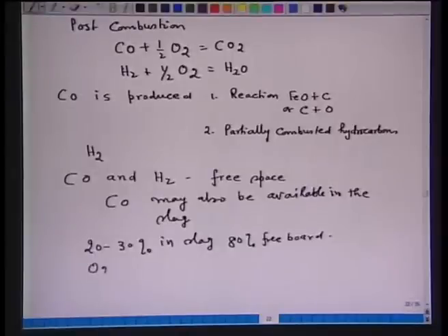That means now what you require? You require to inject oxygen at low speed. If you want to utilize the oxygen completely, then oxygen should disperse well in the freeboard, or disperse well in the slag if post combustion is carried out in the slag.